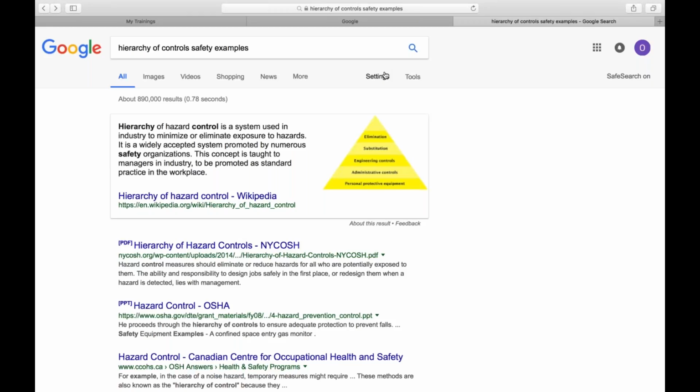And then a method of communicating is also needed to alert employees to evacuate or to take other actions as required, right? A lot of times it might be audible alarms or visual alarms for all people on site, and they have to have an auxiliary power supply in the event of any type of electricity failure. So if we have a PA system, or any type of alarm system for chemical releases, or let's say for fire or whatever, they have to have a backup power supply. The alarm has to be distinctive and recognizable as a signal to evacuate the work area, or to perform actions designated under the emergency action plan, okay?